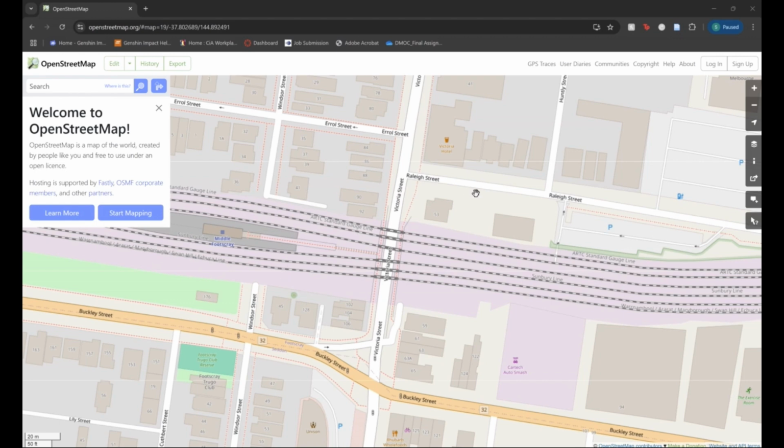If you want to use an existing site as the base of your water simulation, there's an easy way to do that in OpenStreetMap. Google Earth's geometry data is proprietary, so exporting their data is hard to do and only available on Windows. While CAD Mapper is also a good tool, it sometimes has missing geometry in certain locations. OpenStreetMap is free and has accurate building heights.